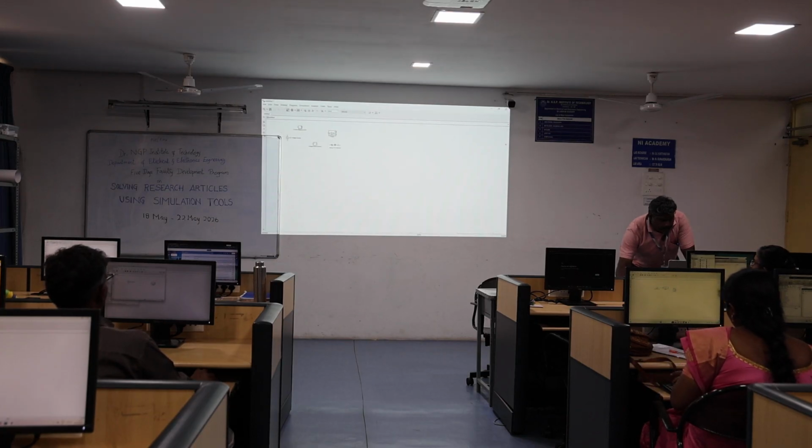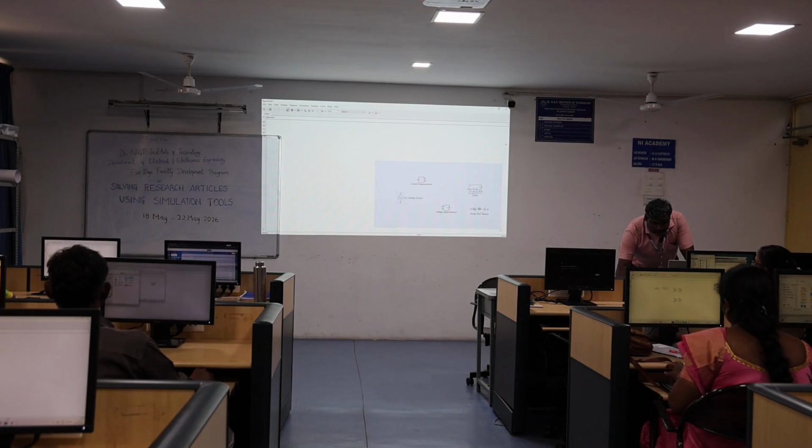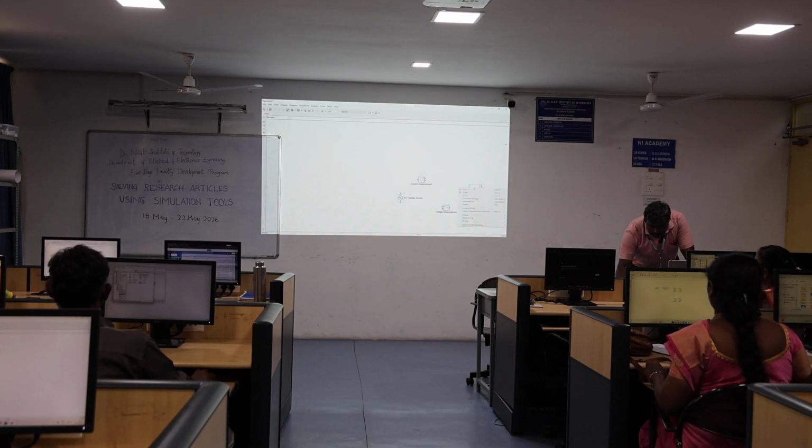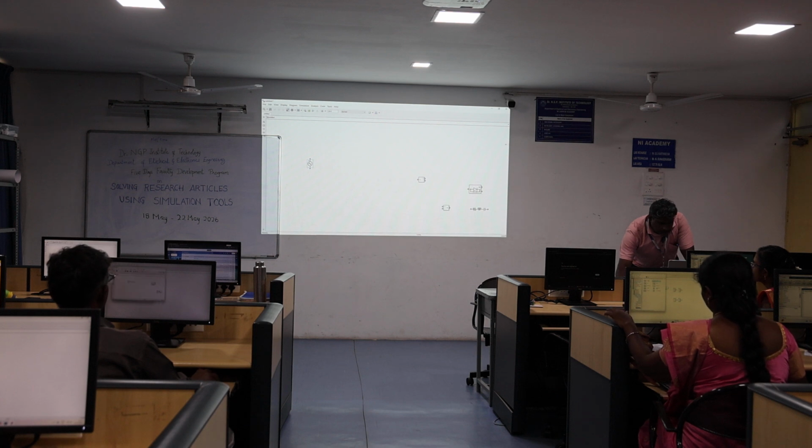First you connect using this component. I want to remove the current measurement and diode labels, so right click, format, show block name. Then first take the source supply voltage, then connect the source current.